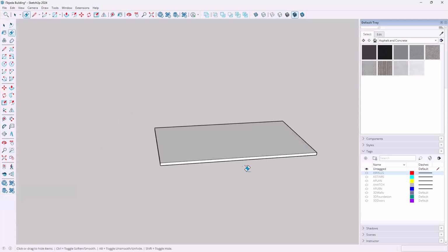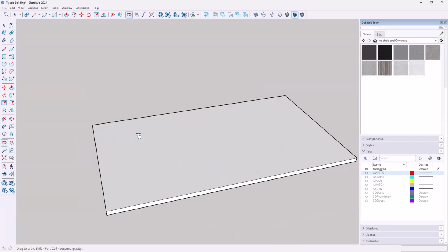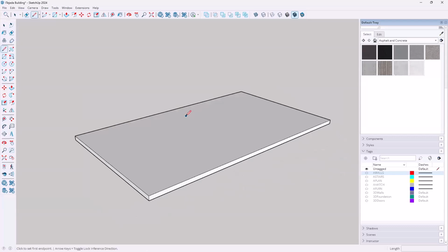All right, now at this point, I have what I need, and now I'm going to draw myself a line. So I'll type L, and I want it to go from the midpoint here to the midpoint on the opposite side like that. And then I'll tap my escape key and my space bar. So I'm getting there, and now it's just a matter of taking this line and moving it up. So I'm going to type M, and it doesn't matter where on the line I pick.